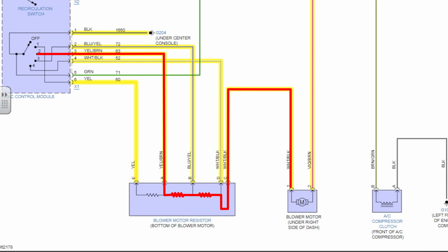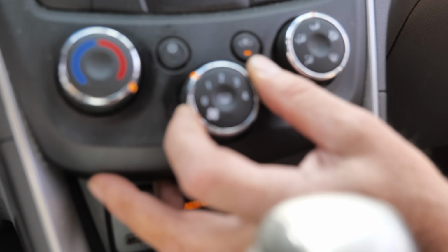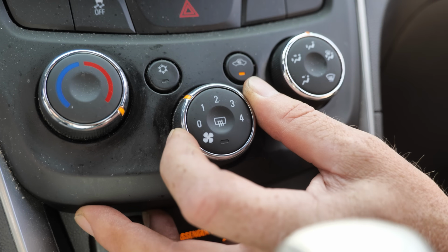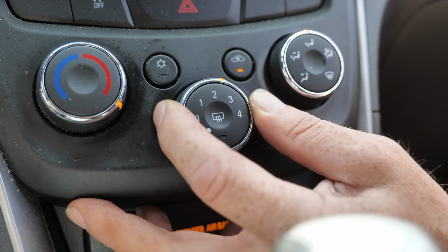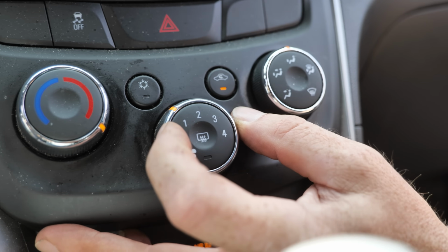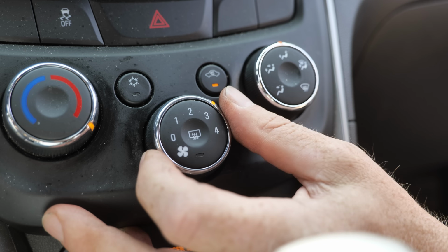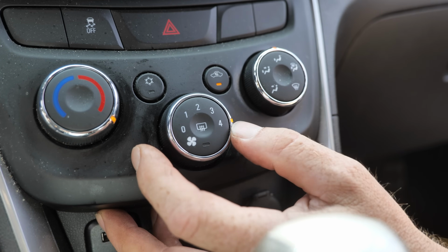And then it'll try to go there. It's traveling through 1 resistor, 2 resistors, and then on its way through 3 resistors to pin E, and then up to 1 on the switch to ground. And so what you would have on the white wire, which is where we're measuring, we would have a higher voltage than ground because it has to go through 3 resistors before it gets to ground. And then as you move the switch, each time you're only going through 2 resistors, and then 1 resistor, and then no resistor. So let's just say hypothetically, we should have 10 volts on the ground here, 8 volts on the ground here, 6 volts on the ground here. My numbers are off. And then, 0 volts, a true ground on 4.